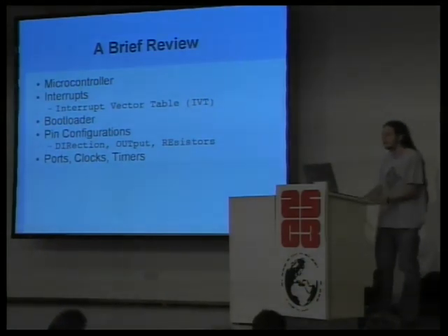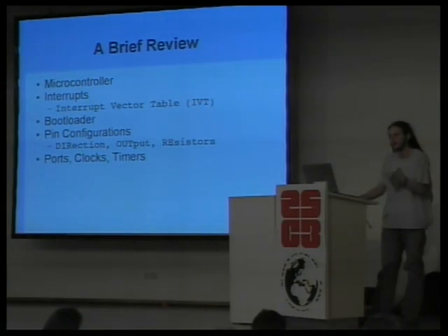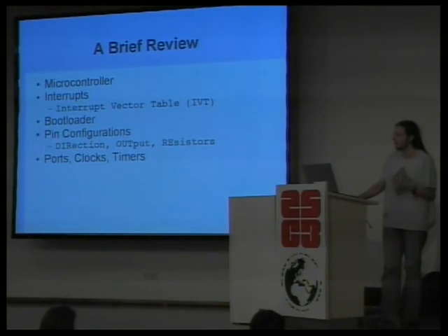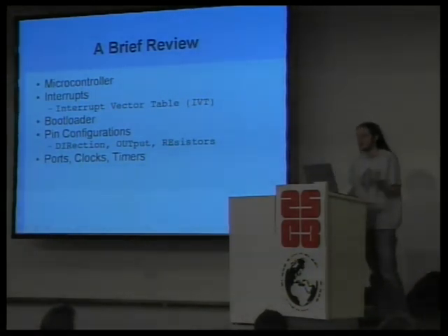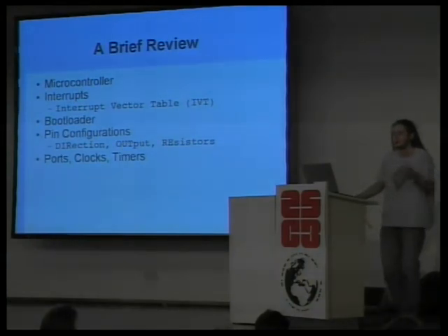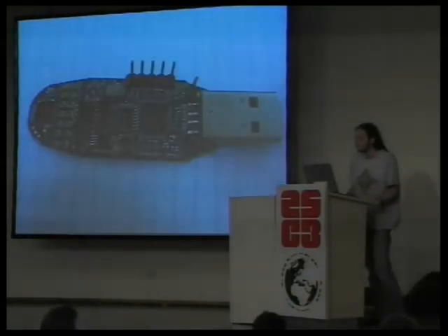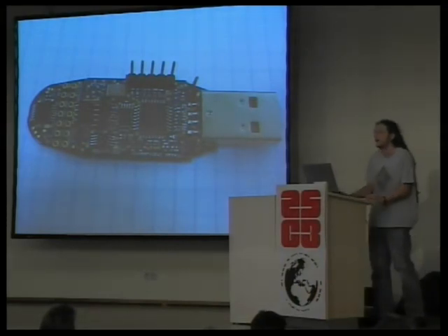So instead, you have individual memory mapped addresses that you write to affect the outside world. So you can change pull up and pull down resistors on an I/O pin. You can change that pin from an input to an output. You can pull it high, pull it low. And there are also clocks and timers and such that you can access by peeking and poking individual addresses. And when you do this, you're not calling a function that exists elsewhere within the chip. You're just writing to an address, waiting a bit, and then reading from another address, or waiting for an interrupt to fire.